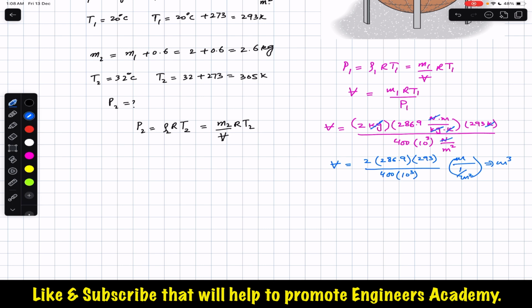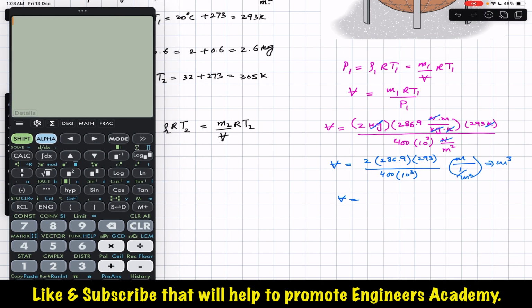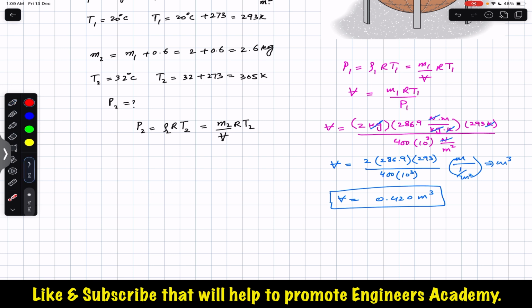So volume is 2 into 286.9 multiplied by 293 divided by 400 into 10 raised to the power 3. So the volume of the tank is 0.420 meter cube. Now just putting this in this equation, we will be able to find P2 for the second state when the 0.6 kg mass is added.